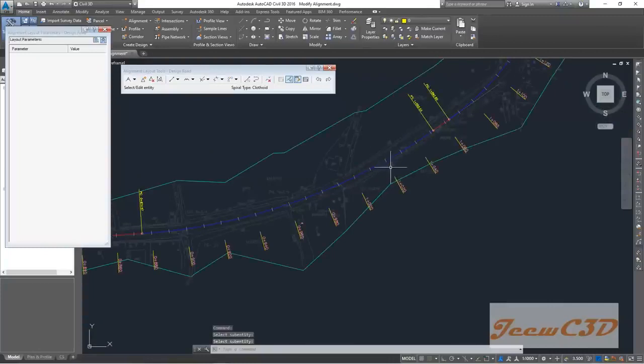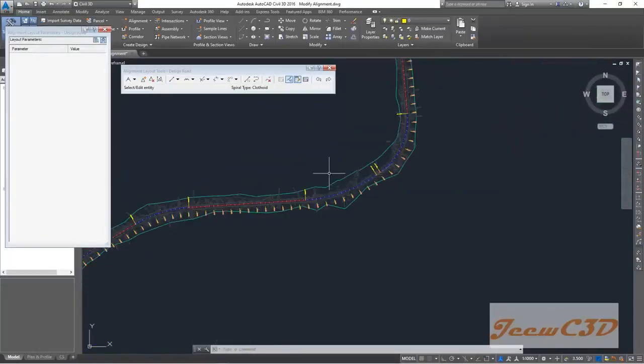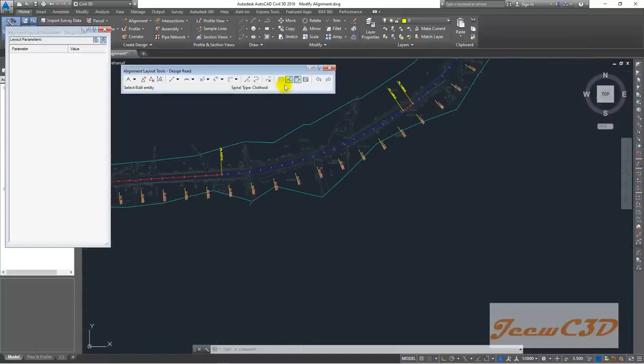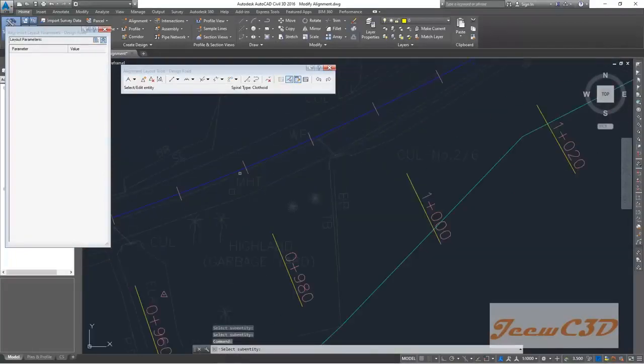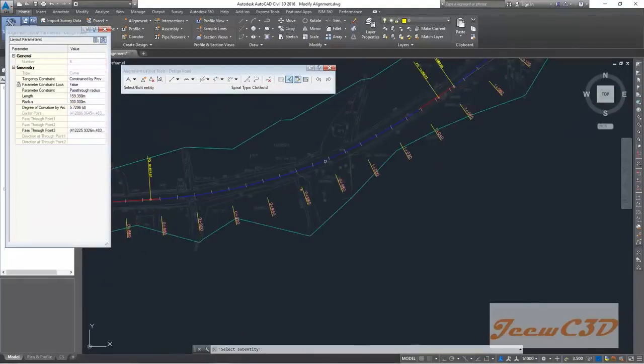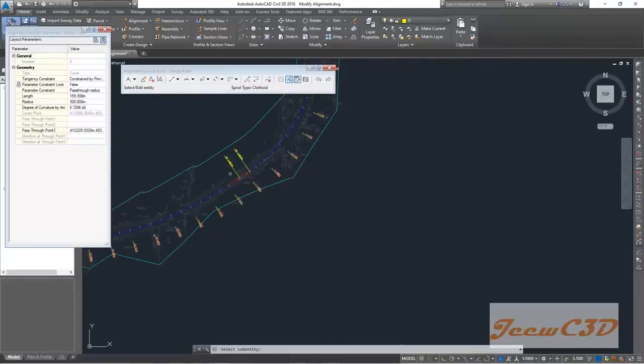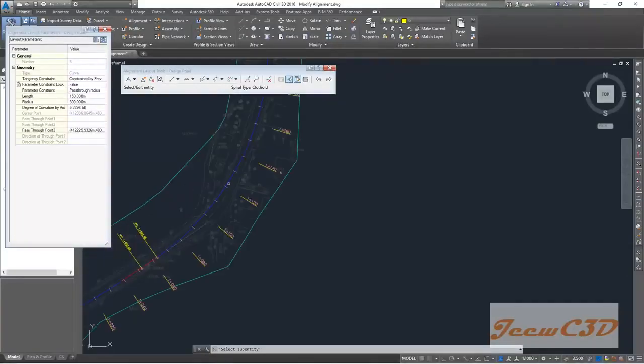Here you have another two curves. Here you can check what to do. I click here and click this curve and you can see this radius is 323. So I go here and make it false and let us say it is 300. Seems okay.